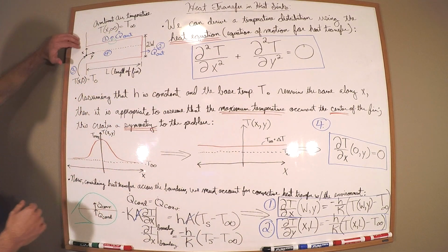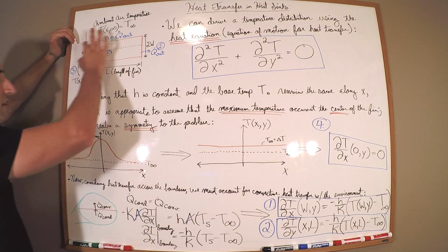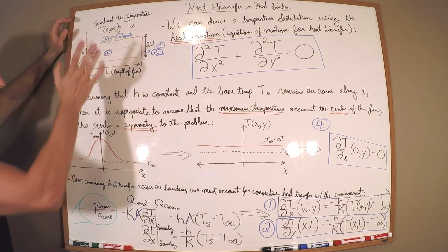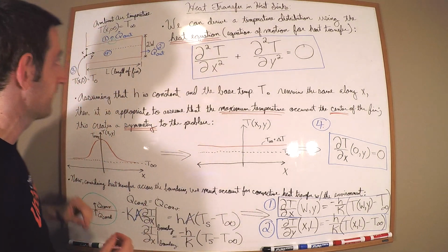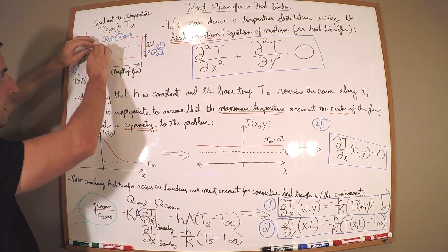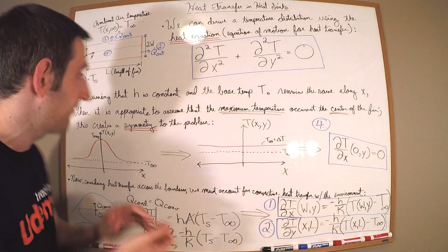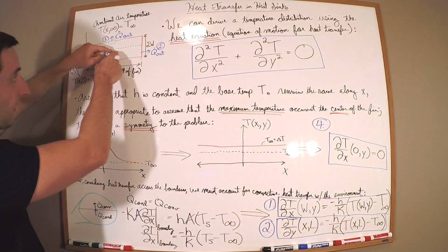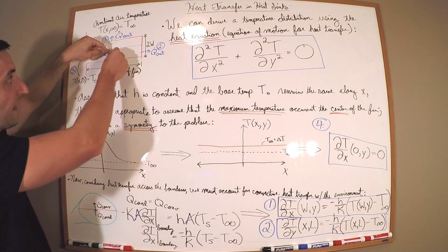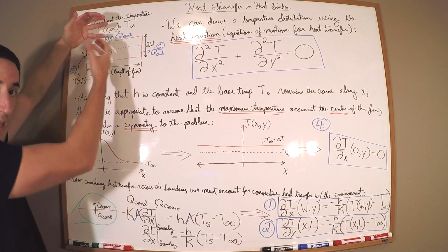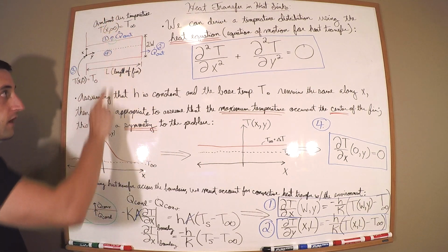So, if we have temperature and energy constant here, what we know is that as it flows into this fin, there are mainly 2 routes in which heat can flow out of it, right? So it's going to flow in here, and then the temperature gradient drives the heat transfer. We're going to have a temperature gradient from the heat here to the very low temperature of the ambient air that's flowing across it. That's going to pull the energy and the temperature down as you move in the x direction, right?